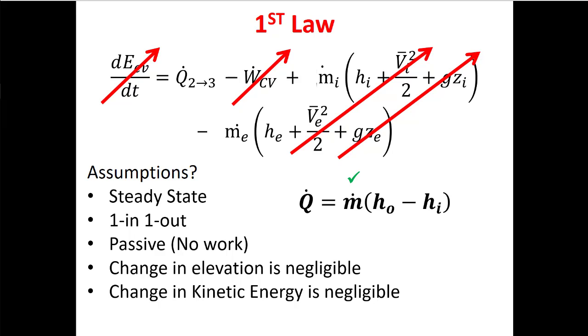So we know the mass flow rate, it was 1 kilogram per, I can't remember, per second, I think, but we don't know either of the specific enthalpies, right? So we have the symbolic solution, but we don't have a numerical solution yet because we haven't fixed the states, right? So we can do that now. Now, here the states intentionally are fairly straightforward to fix because we're at the same pressure, right? This was a constant pressure process. And in one case, we have saturated vapor, and in the other case, we have saturated liquid, right?